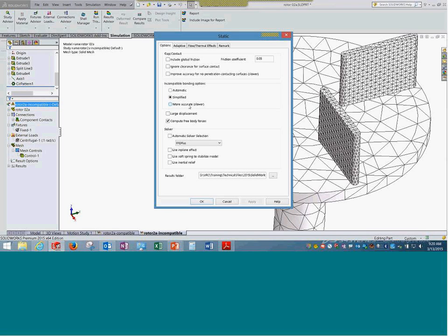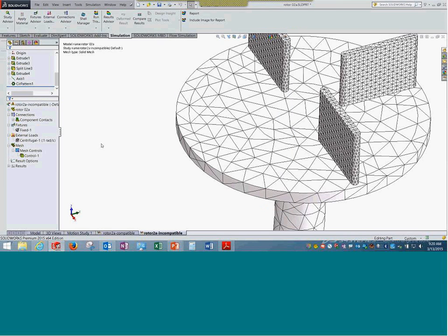So, which you may not visibly see. If you want, you can manually select this option of more accurate, accept it and solve it. You might see a few differences in the results, especially at the local condition, but otherwise there is no big difference. Obviously, if you are looking at more accuracy, if you think the different bonded conditions created with the incompatible mesh are not enough, you can use this option, and that should help you get it more accurate, right?